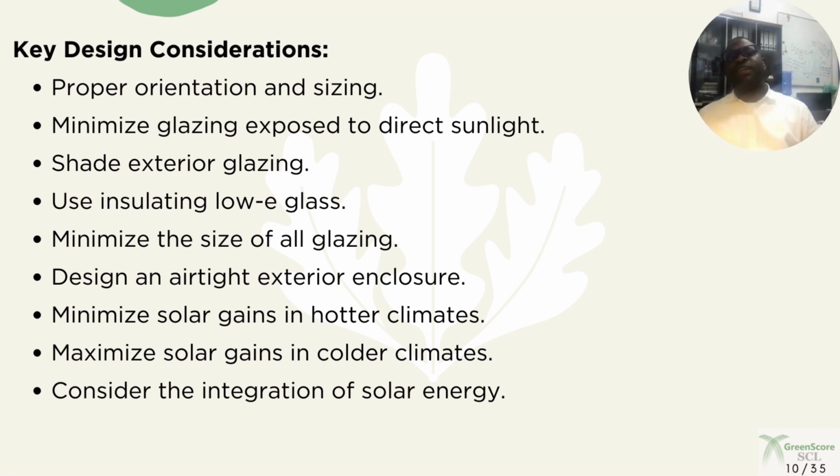Now, shade exterior glazing. All we are doing here is to say that we want to reduce cost of energy. And how to do that is that we must reduce the solar gains or the heat gains. And the more you do that, the less you have to mechanically respond to the solar gains. And the less you have to mechanically respond to the heat of the building, the less energy cost the owner or the client would bear.